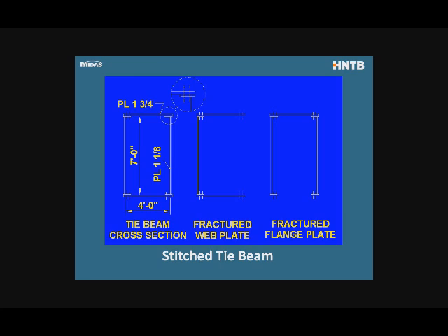This is where the ductility or the insensitivity to bending moments comes in too, with the network tied arch bridge. So we don't really need the moment capacity of the tie beam with network arrangement. Now the idea of the bolted connection is that if any one of the plates fractures, that fracture would be arrested at the bolt line, and so we would not have a progressive fracture throughout the entire cross-section.